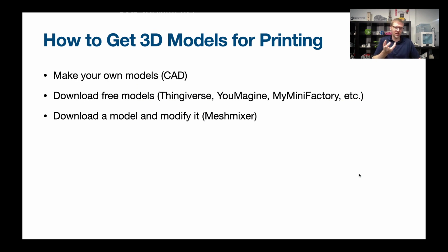That's what STLs are. So when you do your CAD work, you're creating solid body objects, and at that phase you're working in a CAD format. It depends on what program you're working in. But then when you export it to STL, you're turning it into what's called a mesh file. It's a different type of 3D file that's made up of a whole bunch of little triangles that sort of approximate the surfaces and the shape of this 3D object.